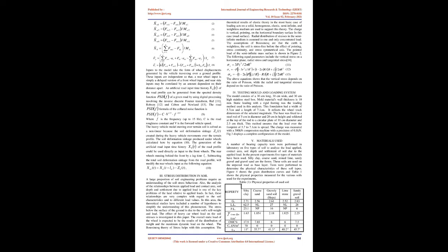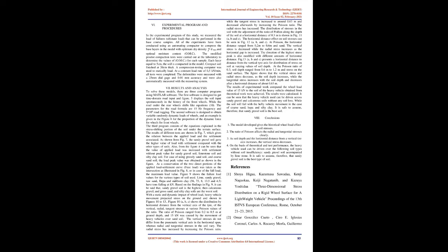The heavy vehicle dynamic model. Fig 1 shows an 8-degree-of-freedom schematic diagram. The model for a 2-axled heavy-duty vehicle ride consists of 3 masses connected by linear spring and damper elements that create dynamic forces based on their relative positions and speeds. Also, the tires, Sharp, R S and Crolla, D A, 10, were modeled as linear vertical spring and damper. The model has 8 degrees of freedom based on Newton's second law of motion.